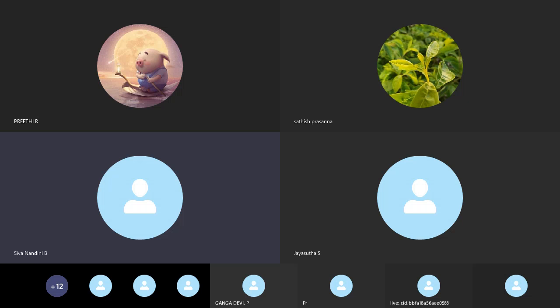Unidirectional means the pin can transmit a signal in one direction only. B means it is a bidirectional pin, that is, it can transmit signals in two directions. Z represents that the type of pin is not defined in the schematic diagram. So all these letters represent the direction of the pin.